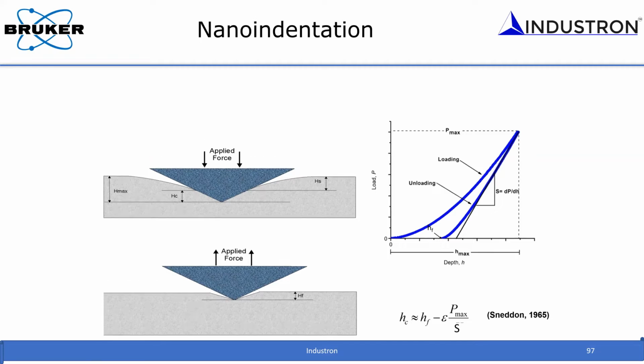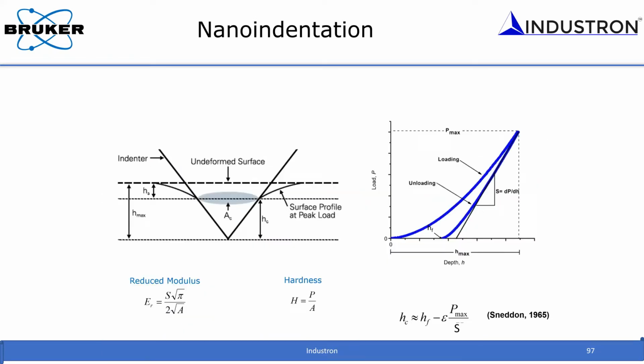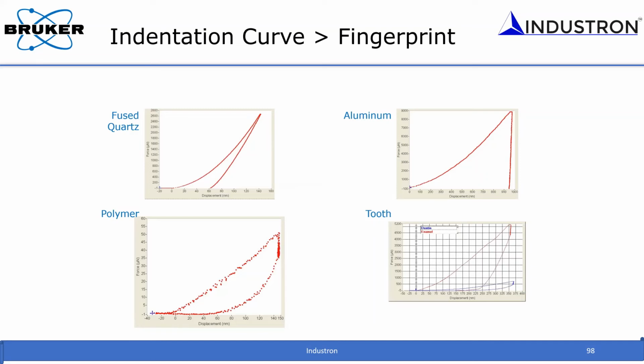And then in the second webinar, we also looked at different types of response that you get from different materials, elastoplastic. In the last webinar, we saw the viscoelastic response of polymer materials, and I also introduced a different concept of measuring properties through a stiffness measurement technique, where you apply a sinusoidal modulated force and measure the sinusoidal displacement response.